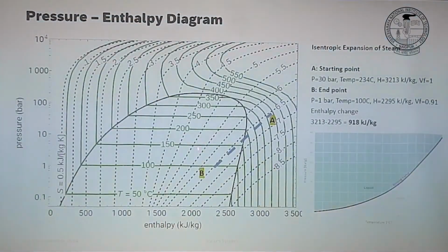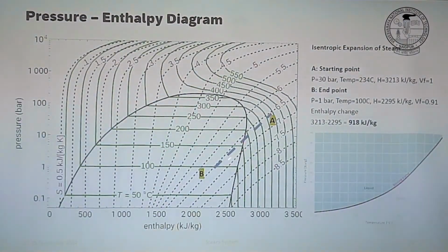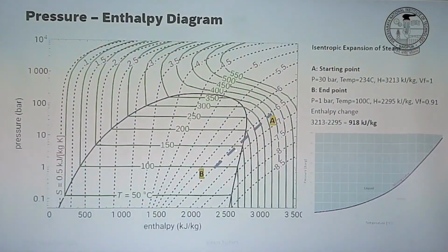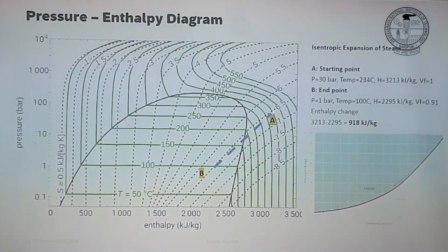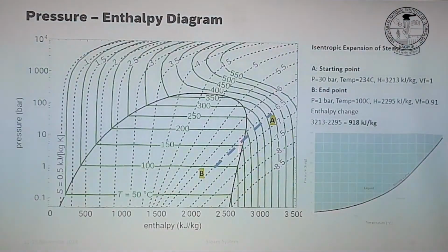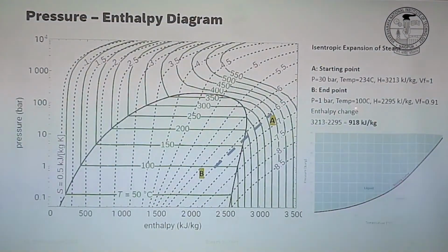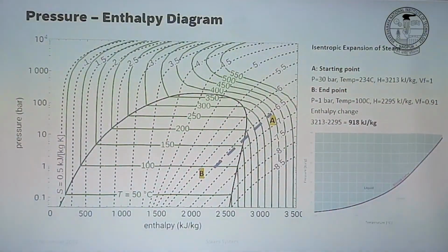So earlier for thermal energy, we moved from here to here. We also saw that if you move from here to here, we can also extract energy. And it's better if you are expanding steam. It's always good to have a very high pressure difference between point A and B. Or we can also increase the enthalpy by superheating it. Right? So we superheat steam. Out of 3 different scenarios, we saw that this is the best way. The lower the pressure here, the better. The higher the pressure here, the better. The higher the superheat temperature, the better.